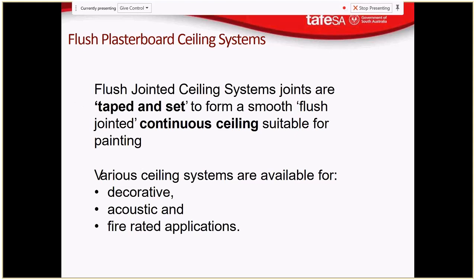But the reason we would use plasterboard or gypsum board instead of, say, plywood for internal linings, or cement sheet or steel sheet for that matter, is that the plaster or the gypsum in the board takes up moisture from the room and then puts moisture back out into the room to help, for want of a better term, provide a bit of a moisture flywheel for the room.